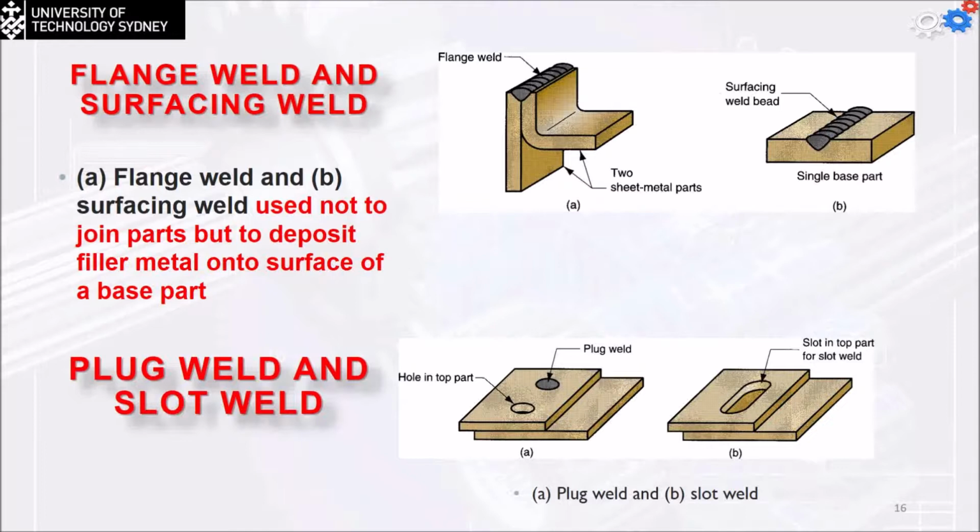We didn't use it yet, so you don't have to throw this one away. You can simply fill it with the welded material and then do the final finishing for it once again. So you just give it an extra life. That's what happens with the high-cost materials for manufactured parts. So usually you overhaul the part by fixing it, filling it with the welded material, then treating it. Also, we have another type which is called the plug weld and the slot weld.